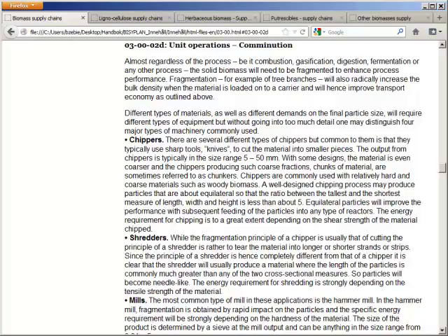If the fragmentation can be delayed until that moment, then different fractions can also be mixed in the input stream to the fragmenter, so that the fragmentation is also a homogenization of the material, and both unit operations, fragmentation and homogenization with mixing, take place in the same unit.